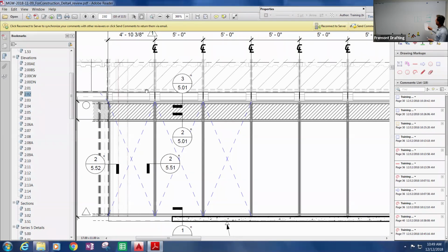And so for racking, for our units, as a unit, I'm a square, and we consider that it's going to stay rectangular. It's going to keep its primary shape, and it's going to do like this as it moves. So as this floor moves this way, my units have maintained their shape, but because of their anchorages, and this is the floor line.